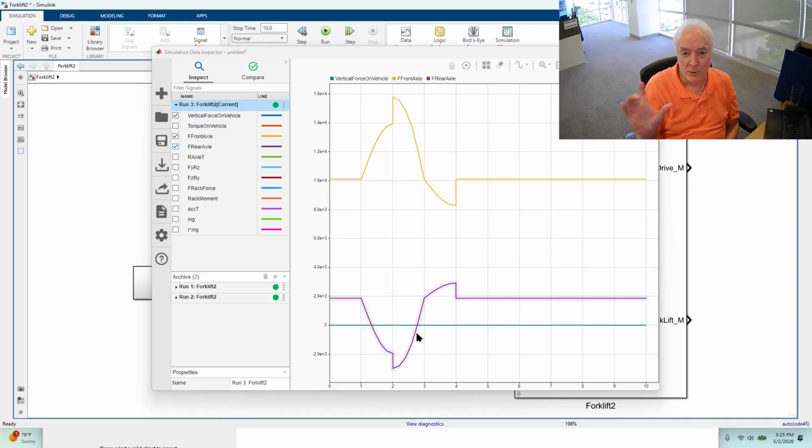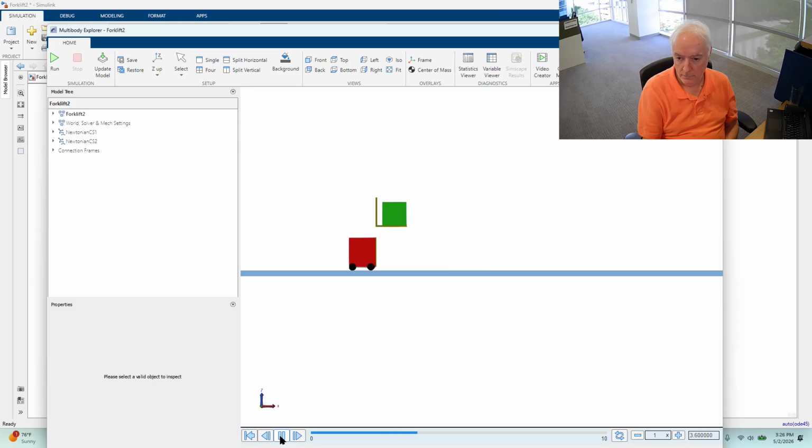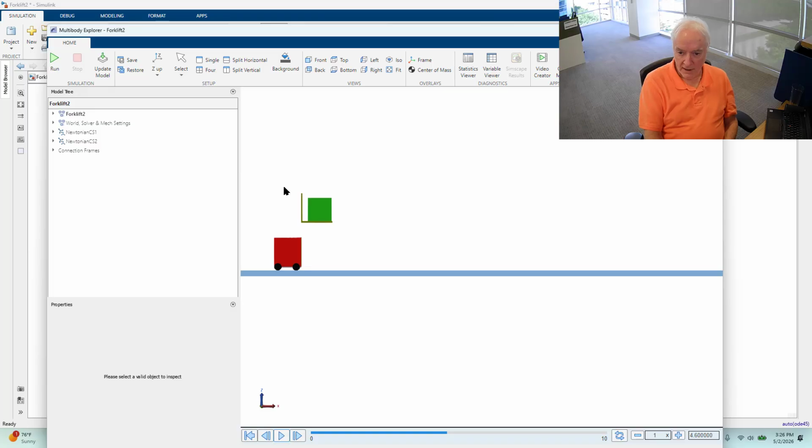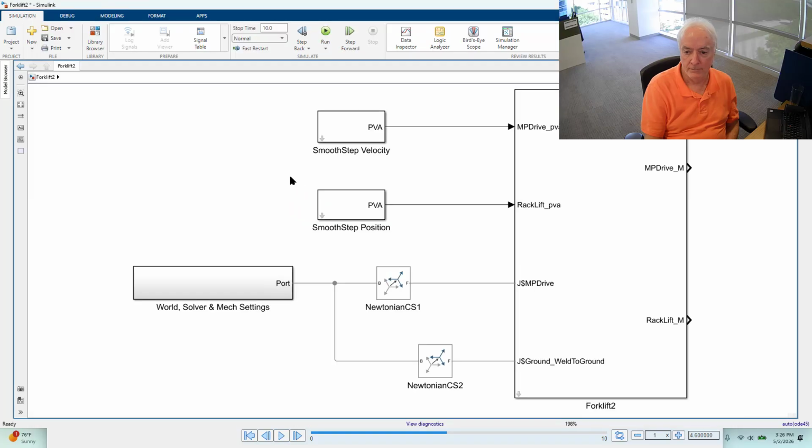Although, again, we saw if we move it forward, things work real well. And I want to get it right up here, and I think it's readily apparent that we try to accelerate the vehicle backwards when the forks are up. We got a much larger moment arm associated with this load right here. And I would suggest let's accelerate backwards and then raise the forks. So that's the way we're going to do it.